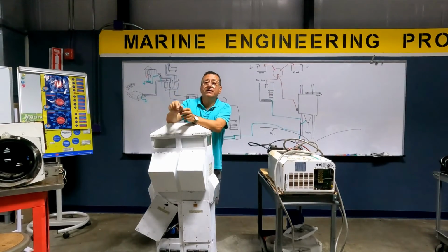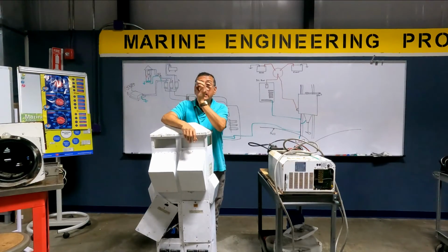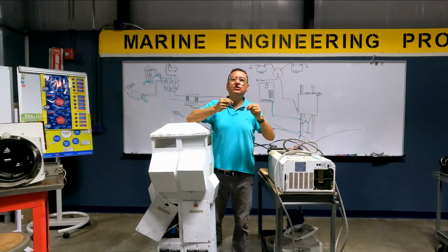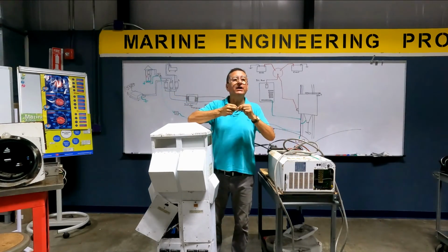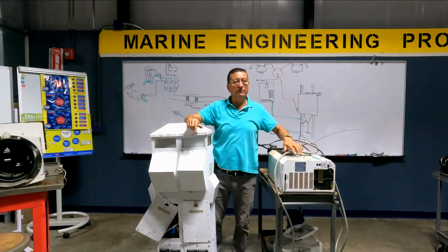This is the difference between a residential and industrial electrician and a marine electrician. The marine electrician has it clear that neutral and ground should be separated. Only at the source of the power are neutral and ground together. After that, they travel in different cables, white and green. Good?